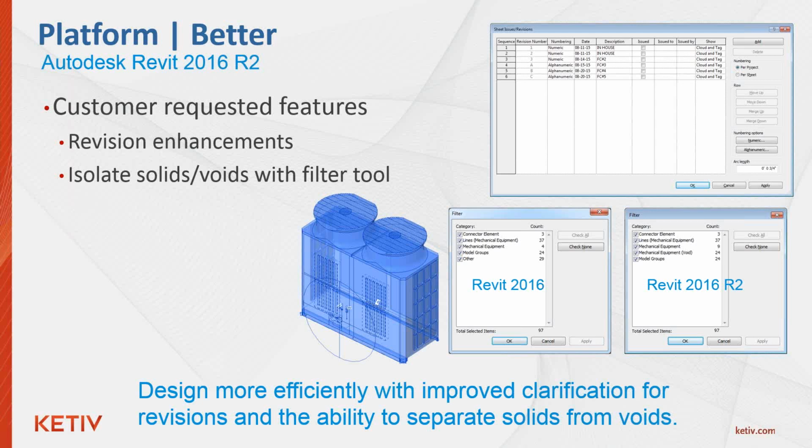All right, so now we have isolate solids and voids with the filter tool. For complicated families containing many geometries, it's often very difficult to multi-select only the void or only the solid geometries to make some bulk changes. This new feature allows the use of a filter tool to separate solids from voids by separating them into two different items in the filter list. The geometries not assigned to a specific subcategory show up listed under the family's category instead of displaying as Other, as it did before.